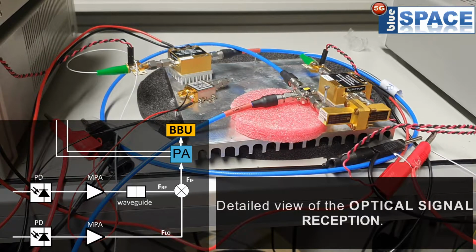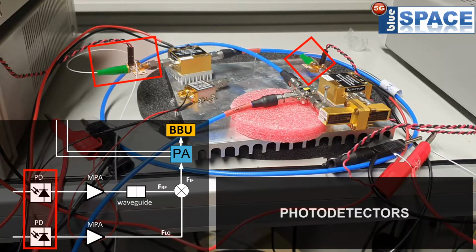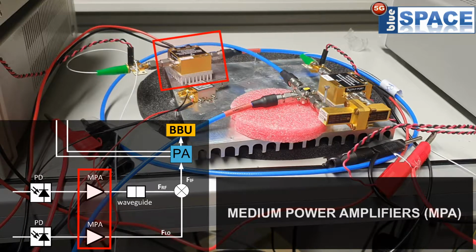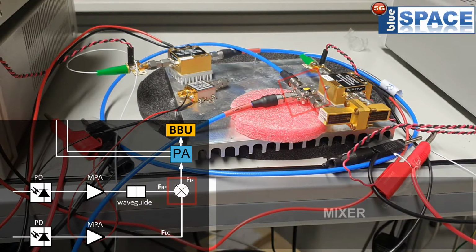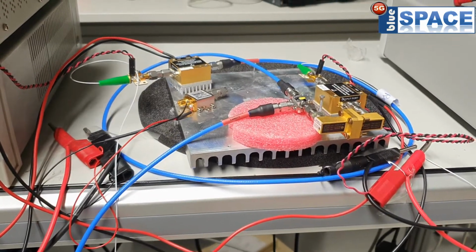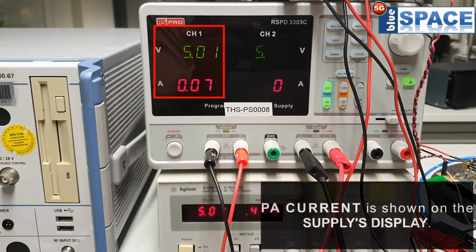This is a more detailed view of the signal reception stage, consisting of 2 photodetectors for the 5G signal and for the local oscillator, 2 power amplifiers, one for each photodetector, a waveguide to filter the 5G signal, and the mixer to move down the carrier frequency. Electrical power amplifier's power consumption is shown on the supplies display.